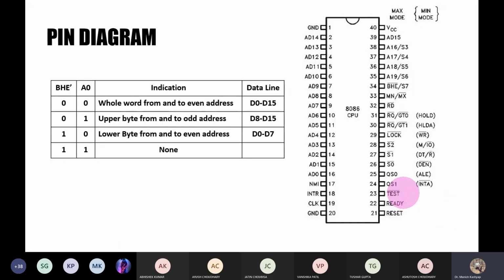Sometimes it will need to be in power. So there is a conflict of power between processors. So the synchronization between 8086 and 8087 or other processors in the system is, that is why, done through a separate pin, which is your test pin, right? So this is the story of this test and ready pin and this reset one, right?